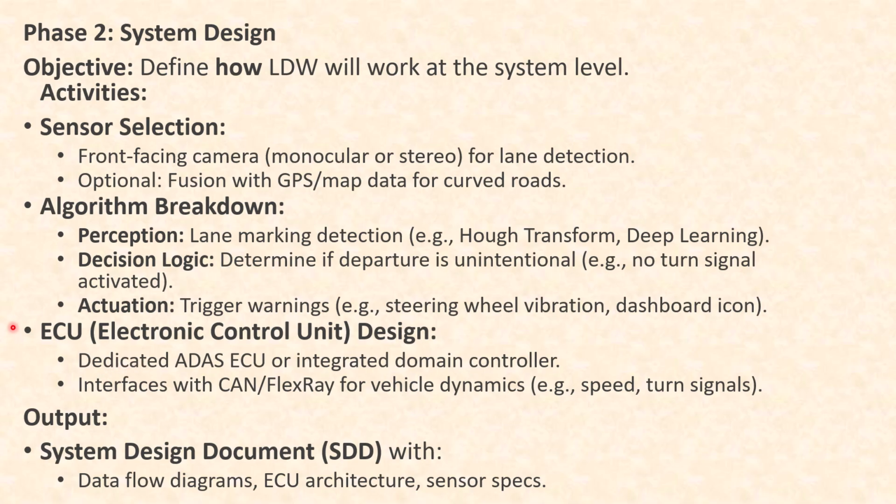ECU design. Now when you say ECU, it involves both the hardware and the software. It must be a dedicated ADAS ECU or an integrated domain controller. As more and more vehicles are moving towards centralized or zonal architecture, whether you have a dedicated ECU or many ADAS functionalities going embedded into an ECU which has other requirements also, that needs to be finalized. And of course, interfaces with CAN, FlexRay for vehicle dynamics. So these are the actual communication protocols.